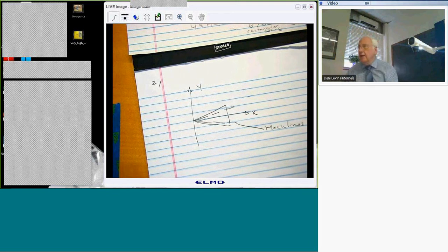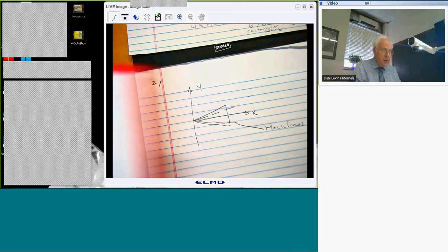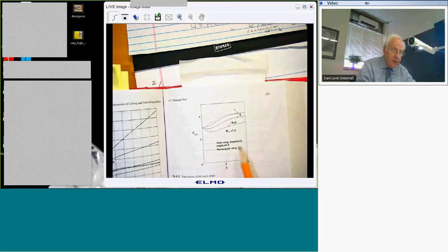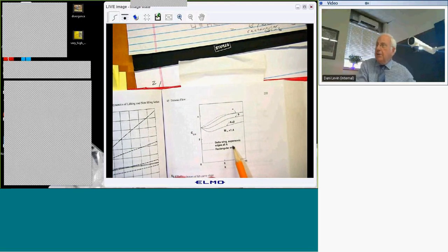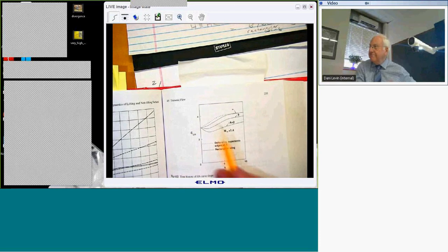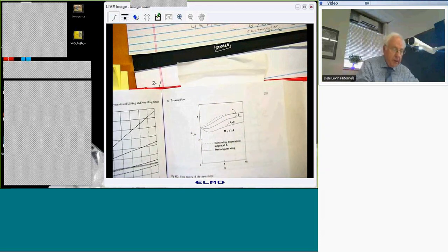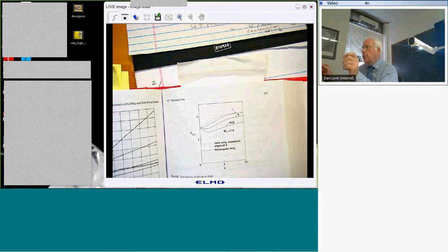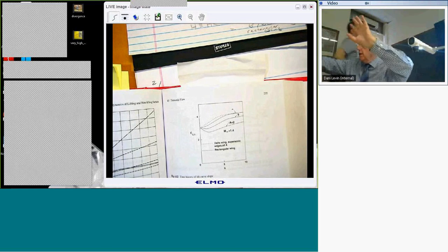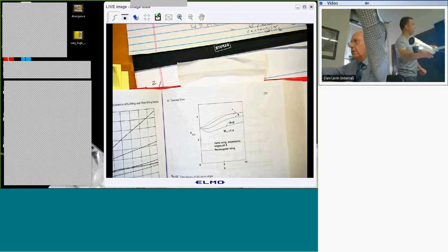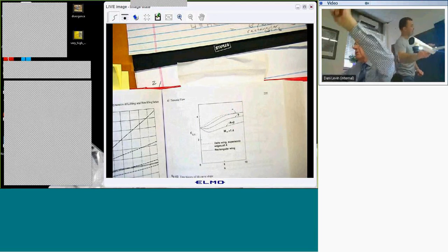And in that case, it turns out, you can show this mathematically, that for that high Mach number, the result doesn't depend on the aspect ratio for CL alpha, okay? Now, for a rectangular wing, it does, because if you think about a rectangular wing, no matter what the Mach number is, there's always going to be some portion coming from the tips of the rectangular wing where the Mach lines this way are on the wing, but the Mach line the other way is off the wing, right? And so there's always a disturbance off the edge of the wing for a rectangular wing.